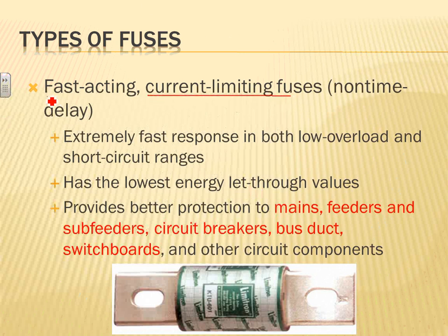These are used on the feeders. I thought just to throw them. If you guys use fuses, this is an awesome guide for which fuse should be used where in application. But dual element, typically motors, fast acting feeders, extremely fast.